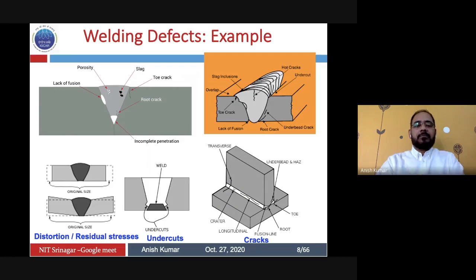And because we are talking about only welds, just to give a few examples of the different types of defects that you can expect in a weld, starting from maybe if the bottom is not filled properly, so you may have incomplete penetration. You may have a lack of sidewall fusion, where the weld material has not fused properly with the parent metal here. You may have porosities.